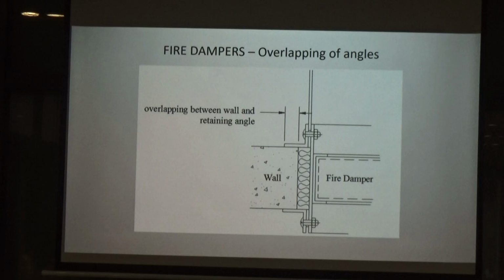Whole damper size, it doesn't matter if it's one or two. So let's say the calculated minimum wall opening size should be 30 mm, for example for the roof side one. So what if they only open 20 mm? Means they open less than the minimum.